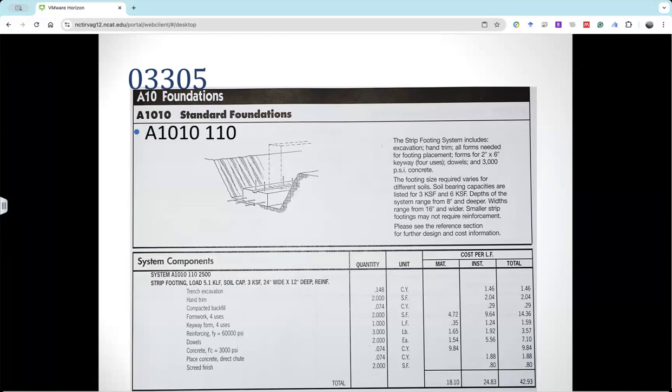You may measure the concrete size, and then do the takeoff for the formwork and the earthwork. We won't take time to see that, but we mentioned it in the last class. If you do a hand calculation with unit cost, then you need to add all of those in. But if you only try to do a quick and accurate estimate, using an assembly will be a way to speed up your estimating process, with pre-combined grouped items in an assembly. So that is assembly estimating.